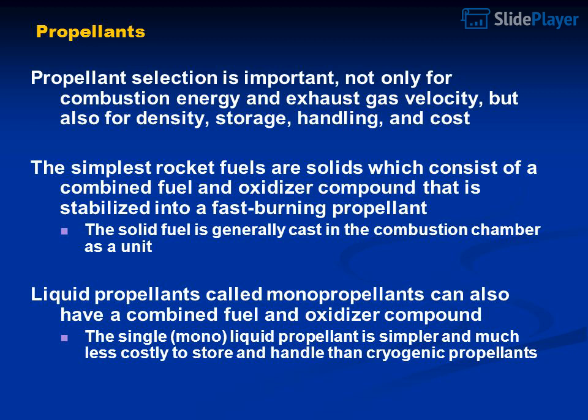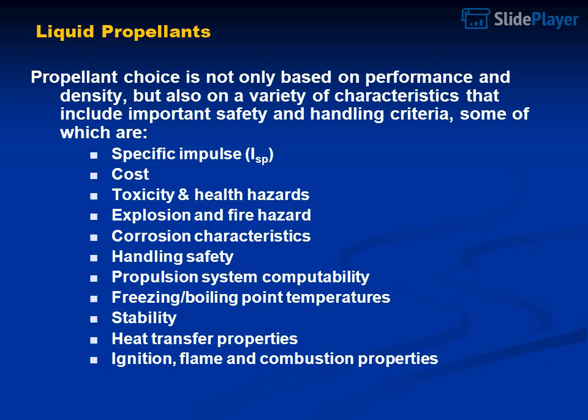Liquid propellants called monopropellants can also have a combined fuel and oxidizer compound. The single, mono, liquid propellant is simpler and much less costly to store and handle than cryogenic liquid propellants.